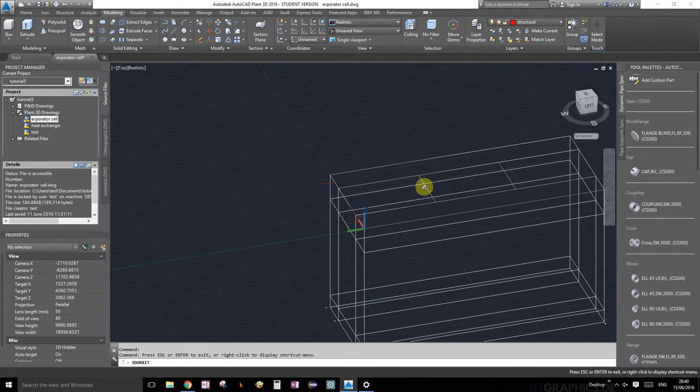I've drawn 2 lines at the top so I can attach the seawater coming in, salt water coming in, those flanges there, just so that I can use the midpoint of these 2 lines as a snap-on point for our flanges. And this is for the big ones where our vapor is going to go to the preheater, heat it, and come back out so it can be used again. Okay, so let's get started.